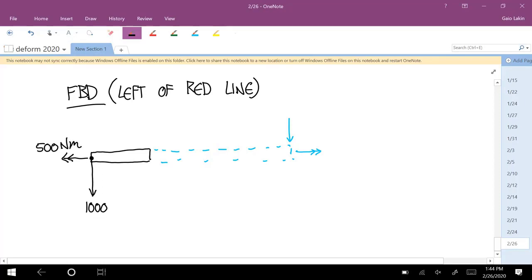And then the internal loads, which you can think of, since the connection between what we're including and the light blue part that we're excluding, as a fixed joint. You can treat this as a force vector. For now, I'm going to call that R. So that's an X and a Y component.